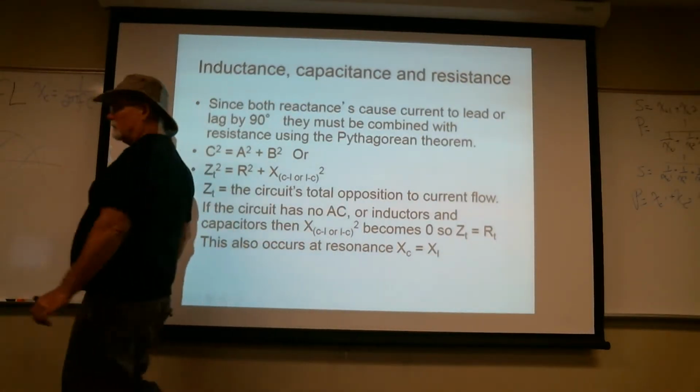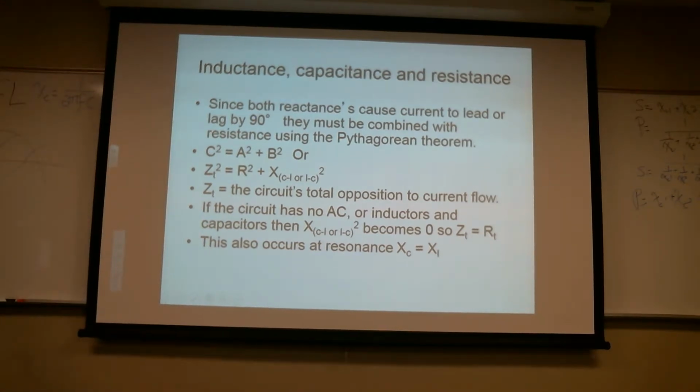Now you might ask yourself, well, what do I care? I'll tell you right now, if I run over there, because I did it just before I walked in here, and push the little button over there and get down to the value that shows me how much inductive reactance is occurring, what I'll find is that for every 0.89 watts we're using in this building, we're paying for 1 whole watt.